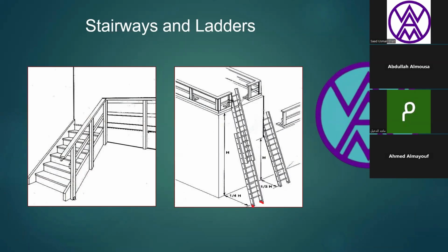If you talk about the top of it, there are two things. If it's more than 3 feet above the roof from where you have attached it, then it's fine. And the second, if it's equal to the roof area, like where it ends, then there should be some support like this. That's also okay according to OSHA. And the angle should be 75 degrees.